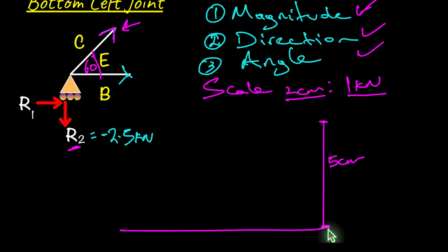So now you need to connect line CE to close this shape, and there is something crucial that you must get. I'm going to show you what that is as soon as I close that shape. So there we go, that shape is closed. This is the crucial bit that will cost you if you don't get it right. Right here is meant to be 60 degrees, and that has to be the case. You can't have the 60 degrees right there, and I'll show you why.